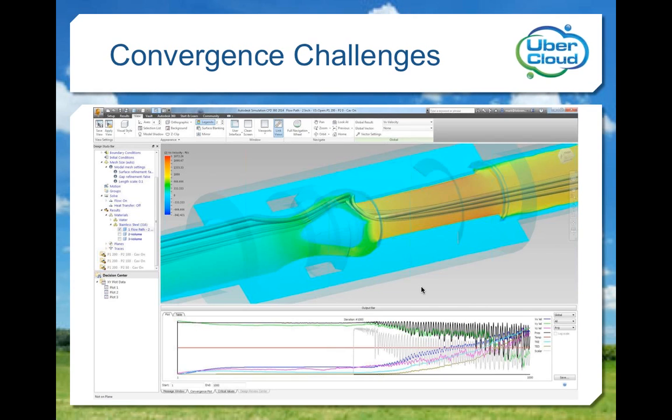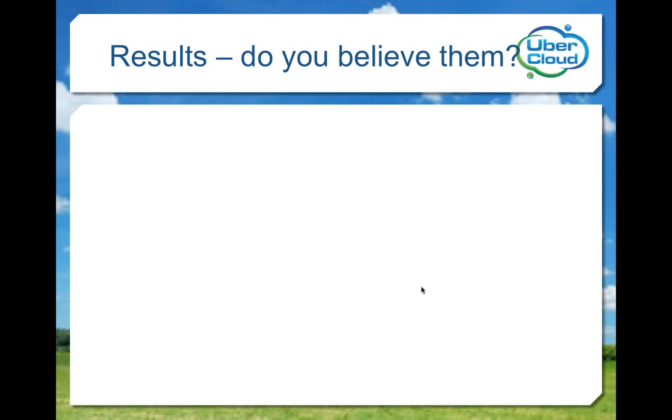As the number crunching advanced, it was pretty clear that the solution just was not going to converge. Somewhere in the enormous matrix simulation CFD was trying to solve, there were static pressure values that were dipping below the vapor pressure of water, less than 1 psi. Thus, for an instant, the incompressible fluid was now a gas. Looking closely at the dithering, I could just imagine that instantaneous change of fluid velocity, fluid density, caused an overshoot that led to another change in density. My colleagues at Autodesk made it clear that Simulation CFD 2014 would have difficulty with the massive vaporization that would occur.